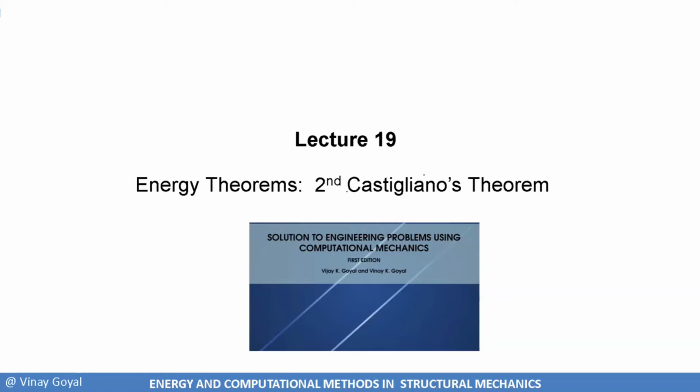And the deflection corresponding to that. Well, we found if I took the strain energy, the total strain energy of the system, and took the derivative of that with respect to the deflection, you will get the load. And so that's a great way of maybe solving problems in a very simple way.